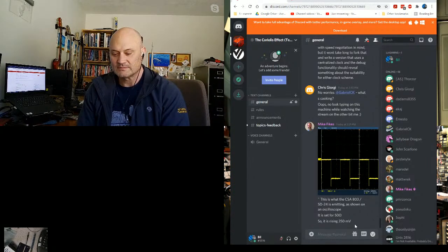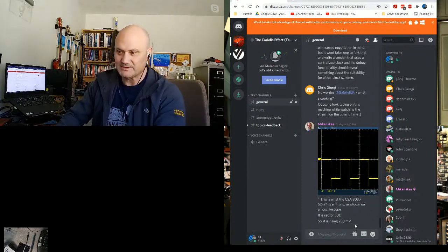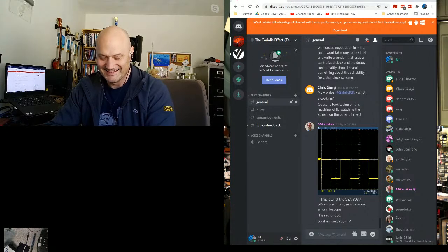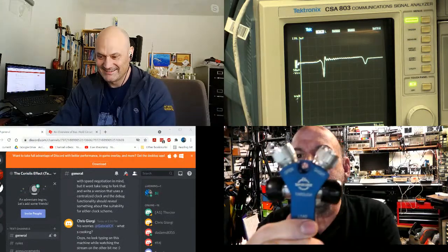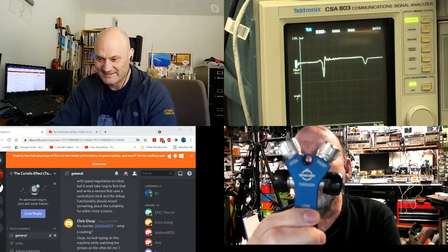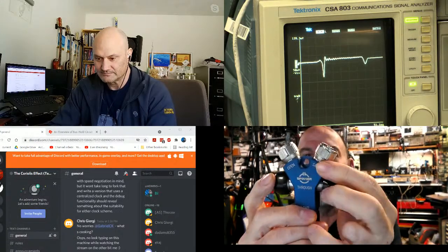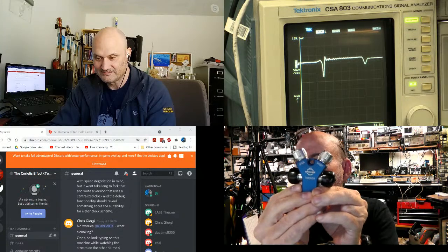So, yeah. You mentioned opens. This came with my VNA. I can't see what you're doing there. You're still sharing the Discord. Whoops. Yeah. Thank you. So this is my VNA calibration kit. This came with my VNA, and it's for calibrating it, so there's a through, but it's got an official open and an official short position on it. Yep. Not that you couldn't make your own, but you might as well have a piece of calibration.